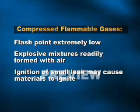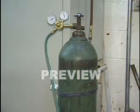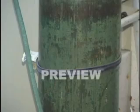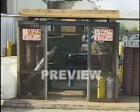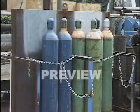To avoid fires resulting from ignition of compressed gases, never roll or drag cylinders when gases are stored, transported, or used. Use a handcart or truck specially designed for gas cylinders. Store all cylinders upright and secure them to walls or bench tops during storage or use. Compressed gases should be stored in dry, cool, and well-ventilated areas, protected from the weather and away from flammable materials.